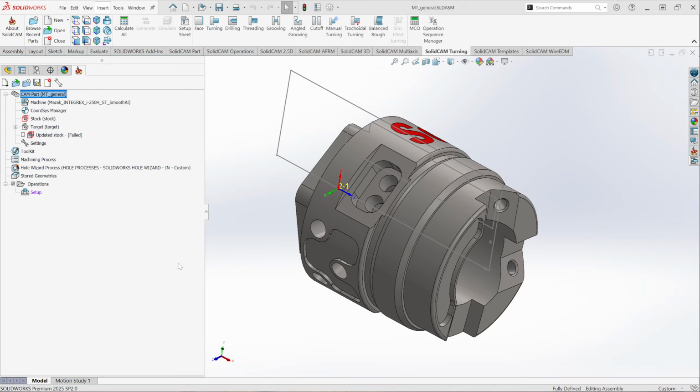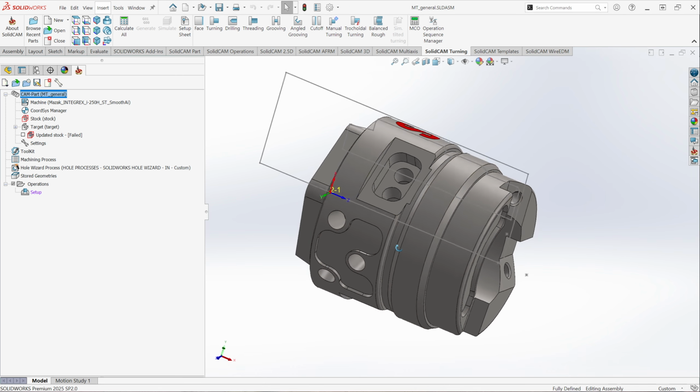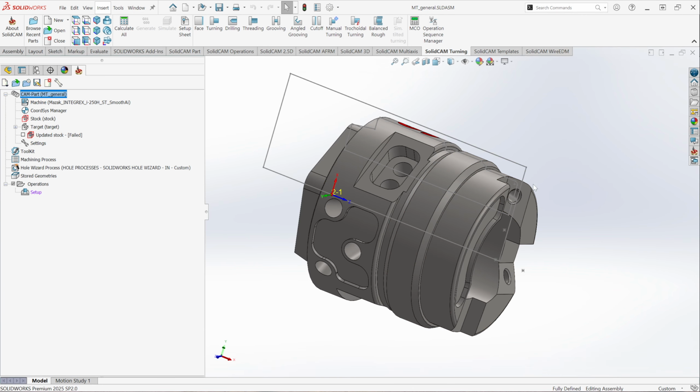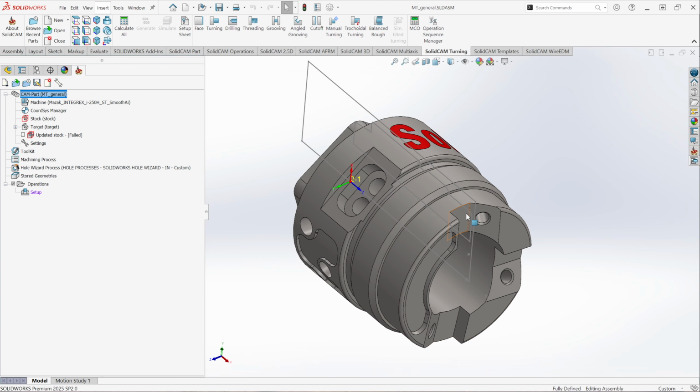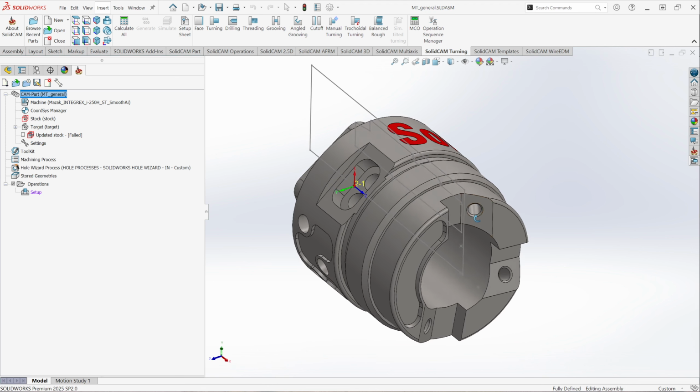In the previous video, we put the fixture onto the main and the sub spindle, and now we are ready to start applying toolpaths to the part at the feature level. Let's look at the part a little bit. We want to face the front of the stock off. I want to rough and finish turn the OD of the part. And then we'll start doing some milling operations, milling different features, whether it's drilling, milling pockets on the OD, on the face, or on different angles.